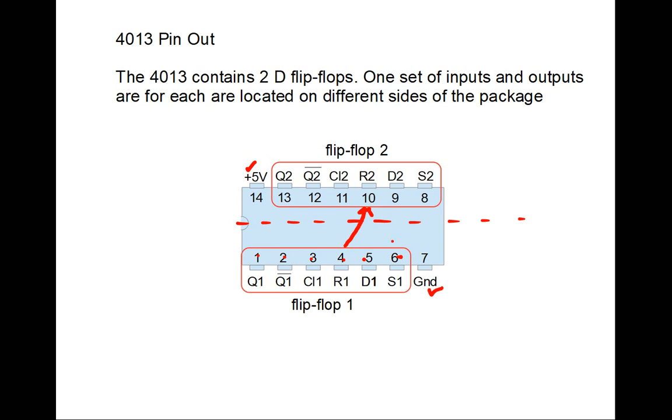To figure out which way is pin 14 and pin 1 versus pin 8 and pin 7, this has a little notch in the edge of it. It's important that you don't put this thing in backwards. Okay, flip it around. So this is the pinout, and just watch this pinout as you actually use it.